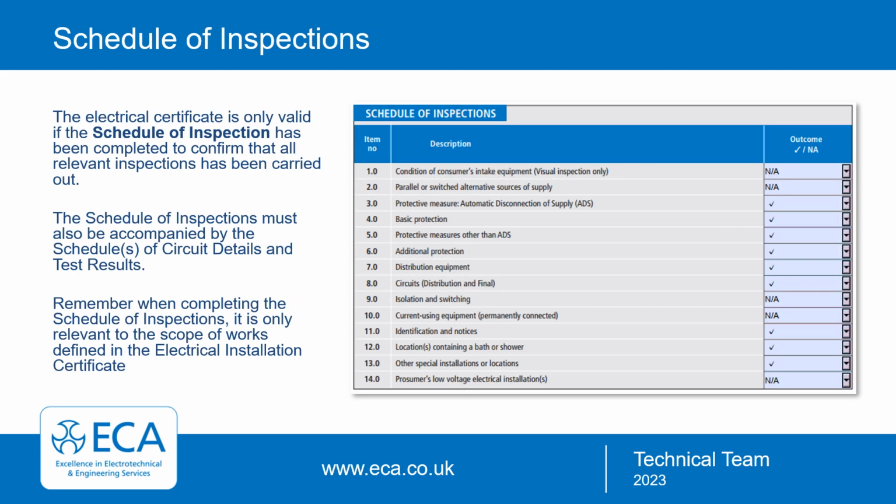The schedule of inspections is now only 14 items, and the electrical certificate is only valid if the schedule of inspection has been completed to confirm that all relevant inspections have been carried out. Some may be relevant to the installation, some may not, and a full list of the example items requiring inspection during initial verification can be found in Appendix 6 of BS 7671, so the aide-memoire is still there. Please remember that the schedule of inspections must be accompanied by the schedule of circuit details and test results.